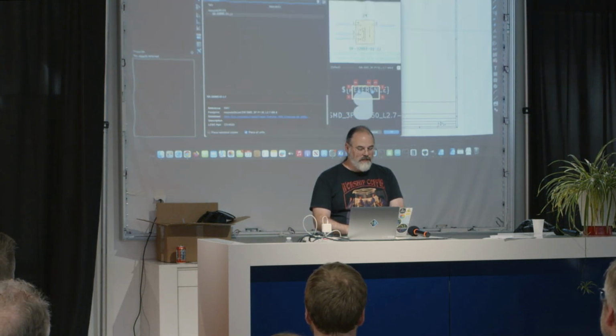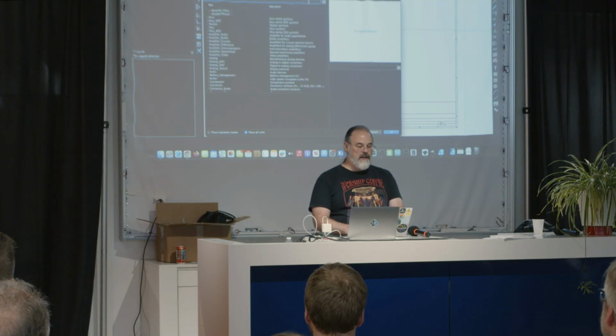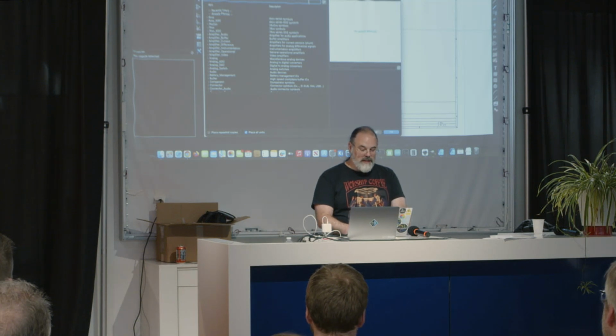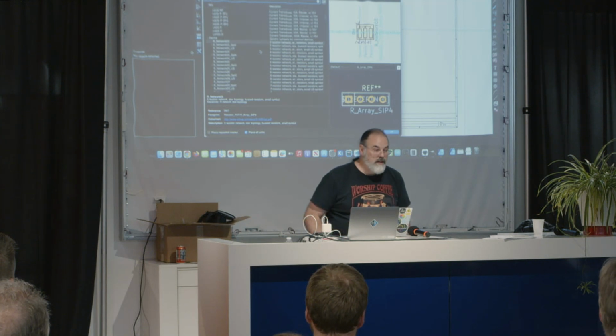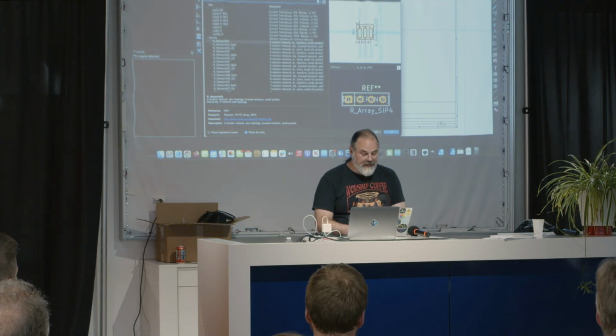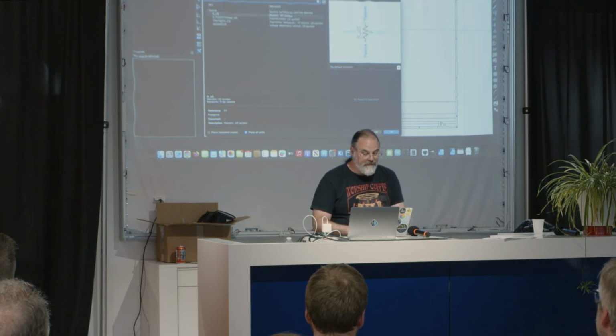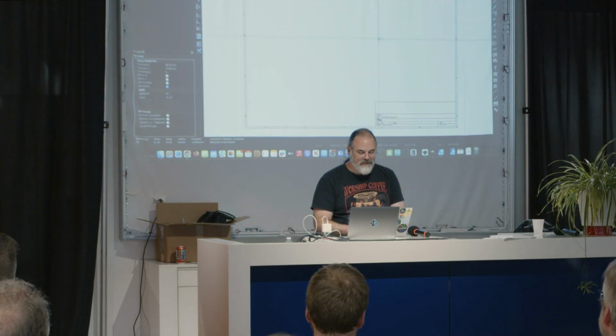So I hit A to go in here to the Add Part dialog, and it starts you right off at the filter. And I know that in this library they have a naming convention with R underscore that gives you kind of a filter right down to all the resistor stuff. And I like the US symbol, because I like the squigglies. It's just what I'm used to, so I'll get that. Let's zoom in a little bit. Can drop a resistor. All right.